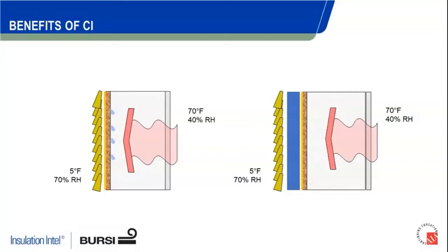So in our section there on the right, we've added this lovely blue line, which is now our continuous insulation in our exterior, over our exterior sheathing component in our wall system. Now, the beauty of adding the CI is not only are we getting that thermal resistance across the whole wall system, but it warms up all those other materials from the CI inward.